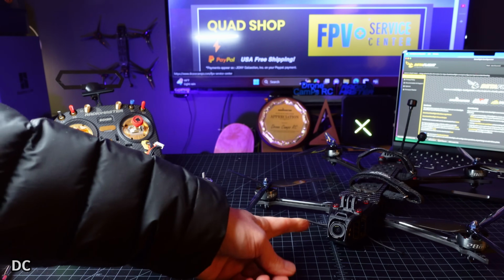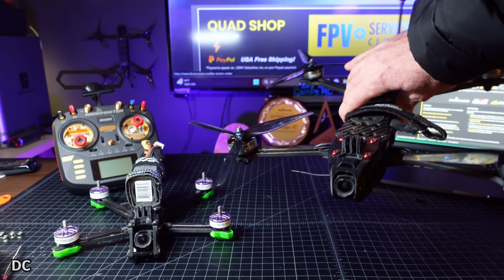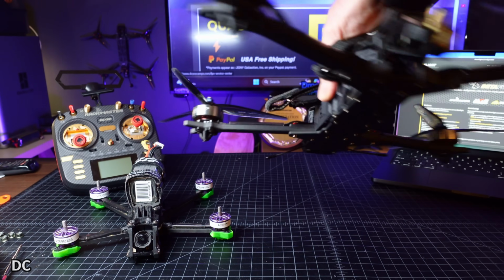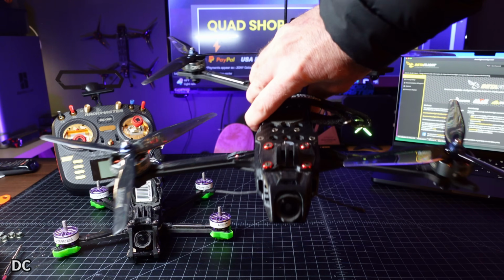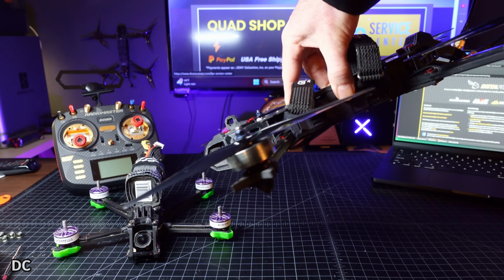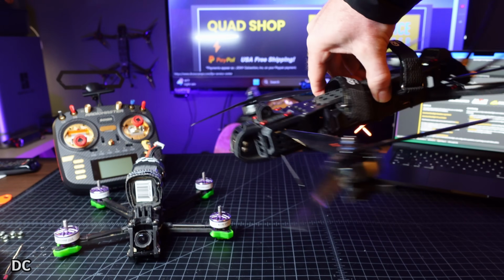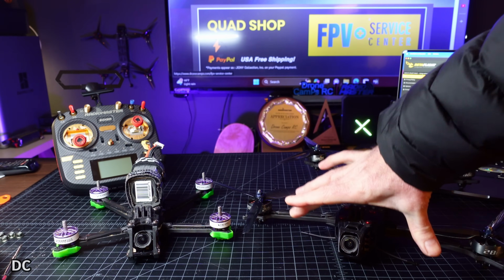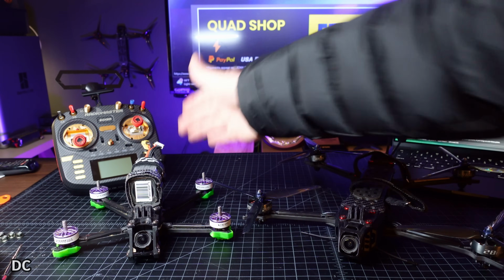But on this front mount type situation, I've talked about this before on the channel, when you pivot and rotate to turn around, say you're coming towards yourself, everything is fine, you can see it's up in the front here. When I turn around this direction, going away from me, still I'm not blocking it. Coming back, totally fine, and going away, totally fine. Total exposure, any axis that I turn. Right about there, we kind of get some line of sight loss, but that's about the only spot, and I've never had a fail-safe with it mounted across the front like this. I'm starting to mount them across the front of my quads more and more, and getting away from that rear mount type of setup.